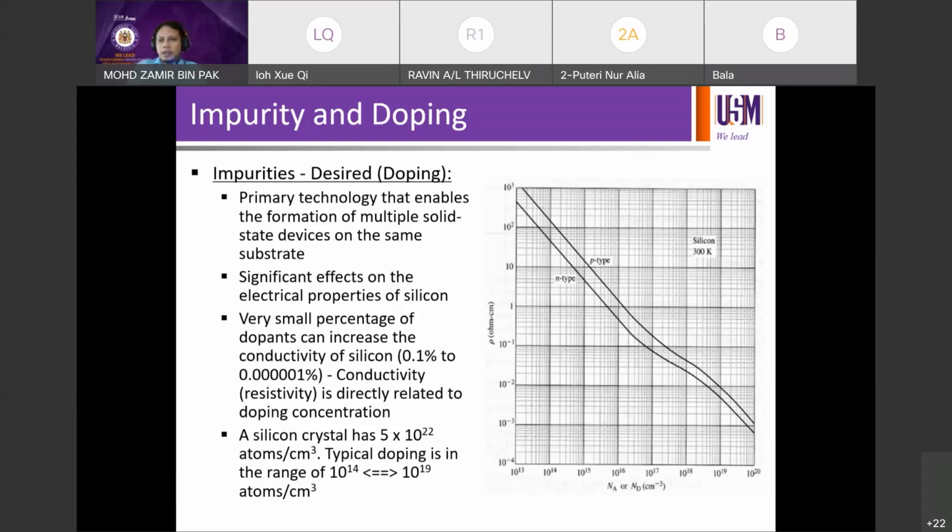If anyone is working on silicon, probably you can see, and if not, never mind. If you work on silicon wafer in the lab, for example, and you take the wafer from the cassette, the holder, you can see the label on the cassette says the resistivity of the wafer is 1 ohm cm, for example. Okay, 1 ohm cm. There is usually a label. So if it's 1 ohm cm, I'm trying to relate to this curve later on. So let's just assume that your substrate is 1 ohm cm, right?